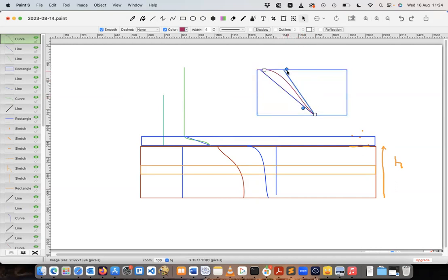When we just forced the concentration to this new value, A would have to diffuse in, and then slowly the whole profile will shift over and settle down to the new profile. So that's what we expect to happen. That's why we've been writing the balances that we have, because it takes time for things to settle into a new steady state, and so we need unsteady state. So that's generally what would happen.